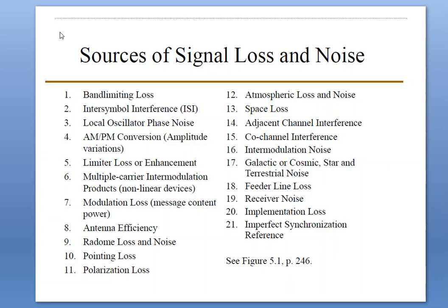And the next one, implementation noise. Now, implementation loss. The loss of performance is the difference between the theoretical detection performance and actual performance due to implementation imperfections such as timing error, frequency offsets, finite rise and fall times of the waveforms and finite word length of arithmetic. So this is regarding implementation losses.